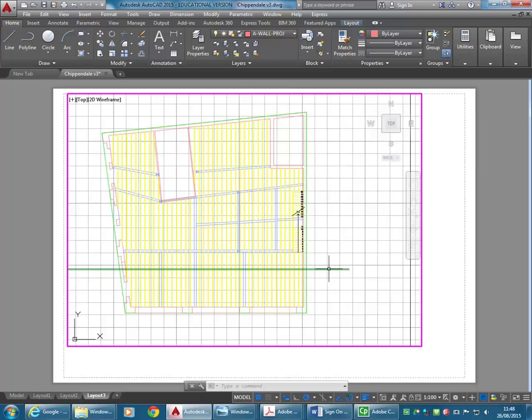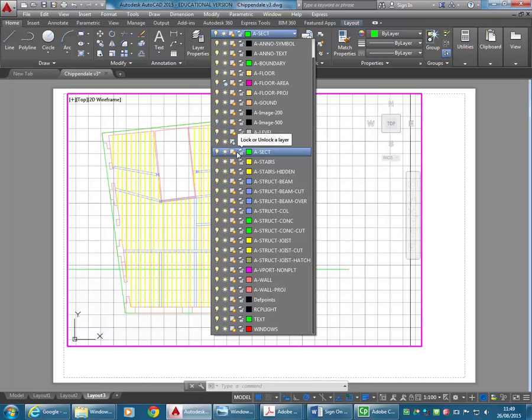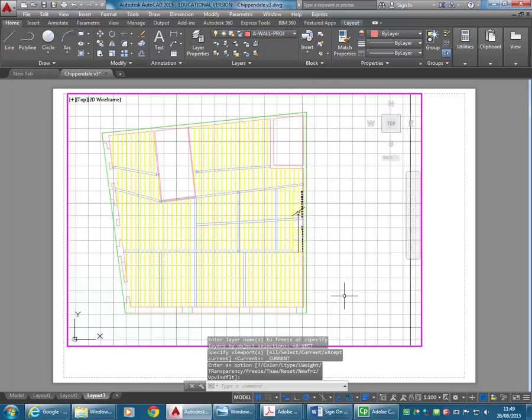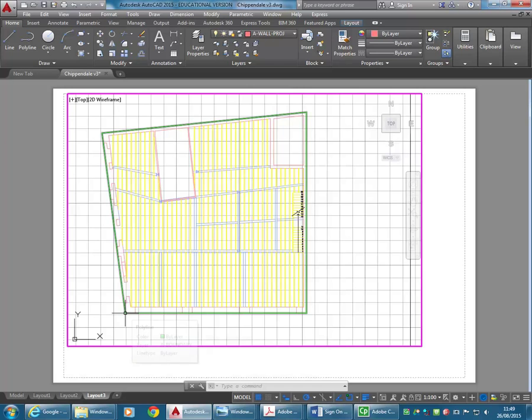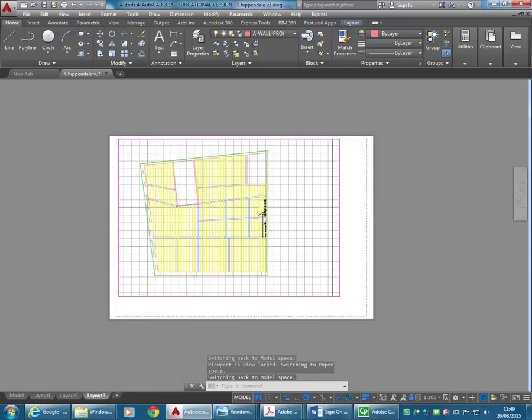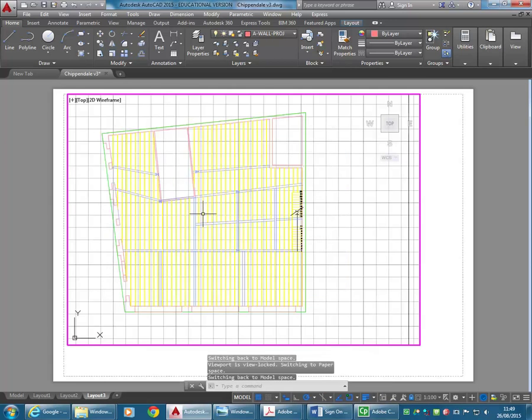And the section line as well, I probably don't need to show for the time being in this reflected ceiling plan, so I will freeze that as well. And then I don't want that position to change either. I want this position to remain exactly as it is, and the scale to stay as well. So next to the scale option, 2 buttons to the left, you've got the option to lock. So with that, once you click on the padlock, now if you zoom, it'll zoom the whole page and doesn't change it. So, because everyone forgets.